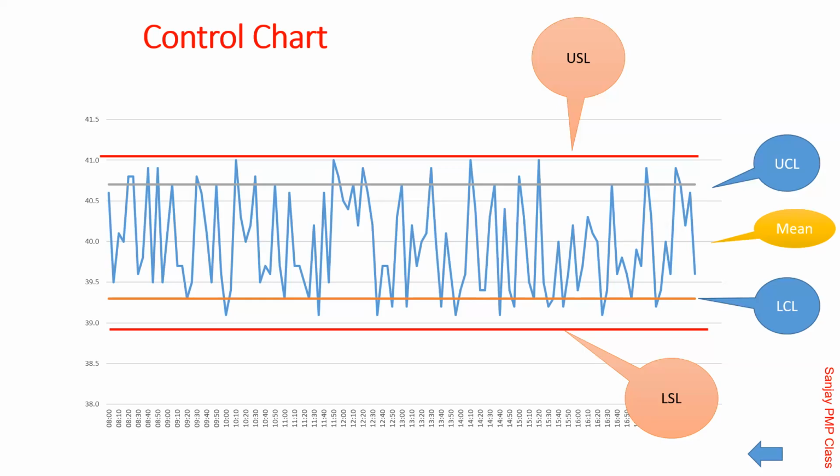If it is above the control line or below the control line, it will go. It means there is some change in the process. For example, if it is a machining component, then there is some change in the process. Maybe the tool is blunt, something of that nature. So if it is crossing the upper control line, soon it will cross the specification, the USL also. Correct, exactly. So everyone got this feeling of what Sanjeev is saying, friends.